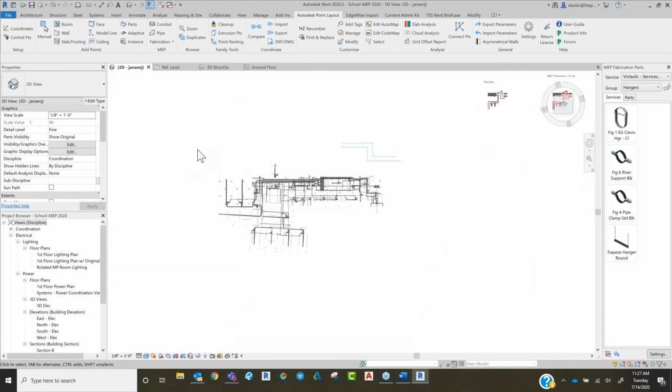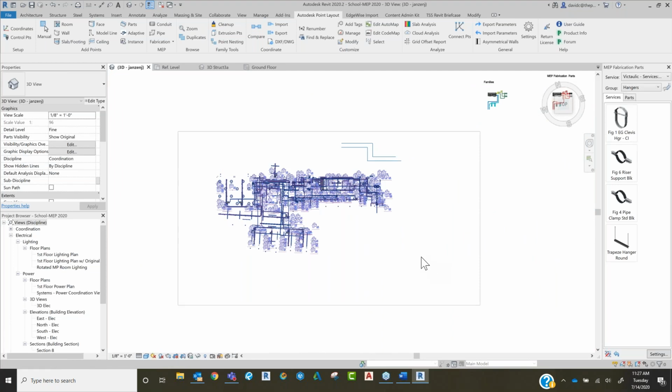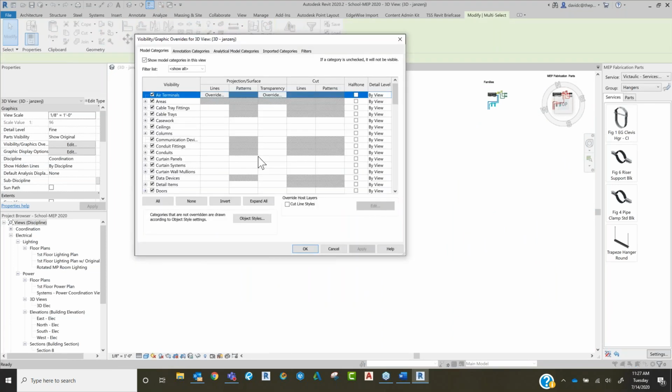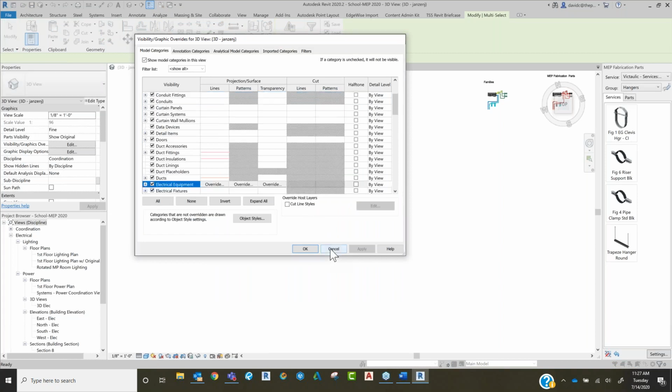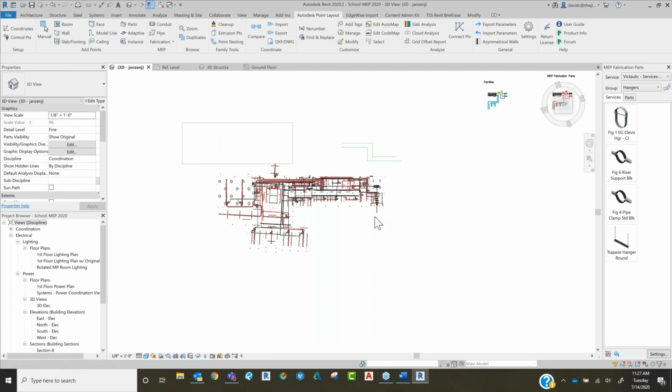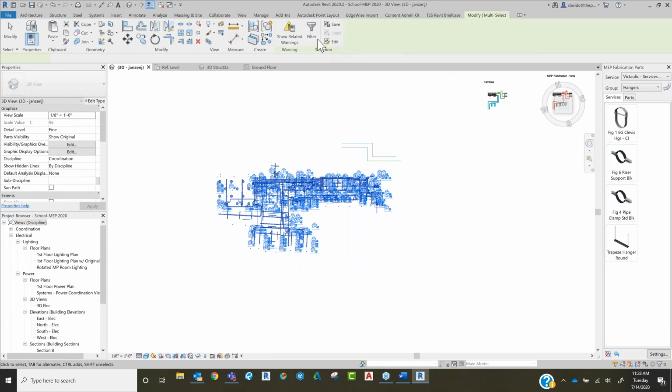You know what? Maybe I'll be a little bit smarter about this and see if I can VV. Oh, what am I doing? I'm not hitting VV. I'm trying to get the filter. I'm going into visibility graphics for some reason. Oh, it's Tuesday. But let me grab these. I'll go ahead and run my filter really quick and see if I can find any panels.